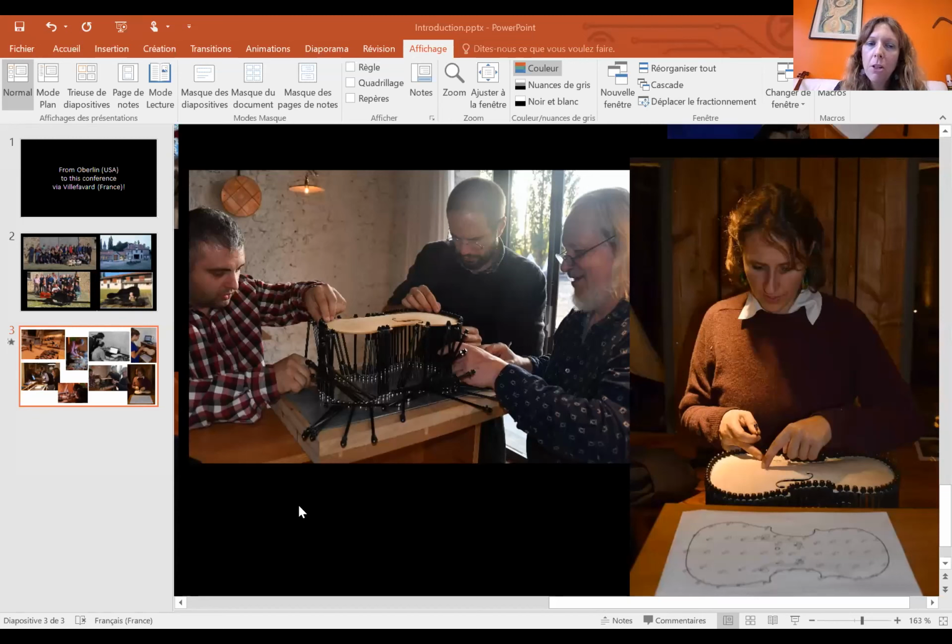Well, sorry, you didn't mention as well that you designed the system because you have the feeling that the plates, when they are assembled into the violin body, are closer to a pinned edge condition because of the ribs than they are to free plate conditions. And so you feel measuring them this way should give you something closer to how they behave when assembled. Indeed.